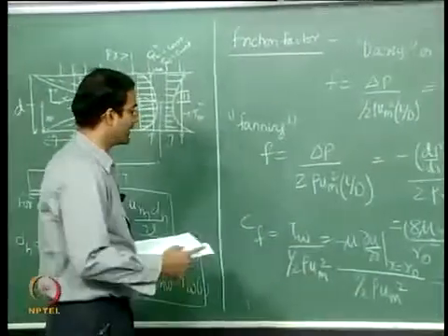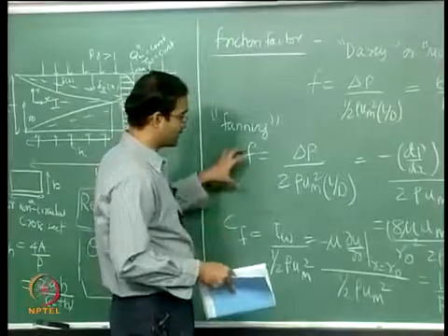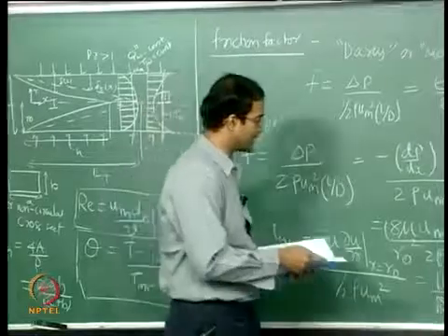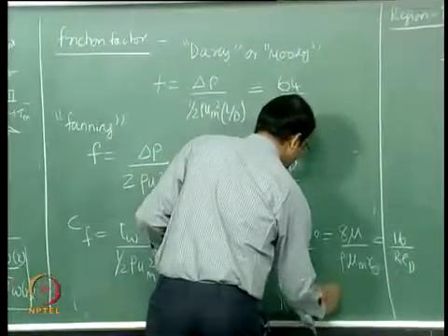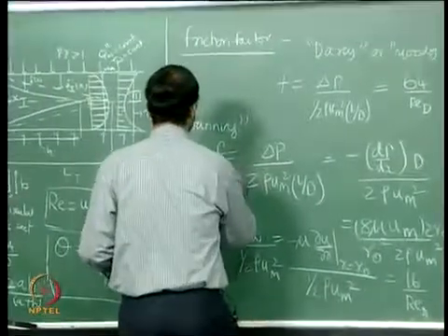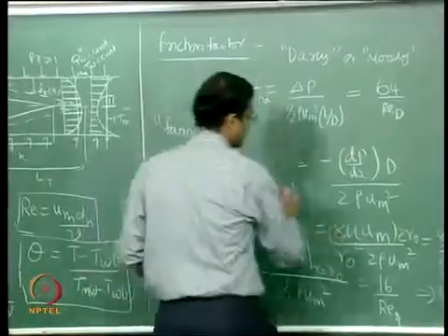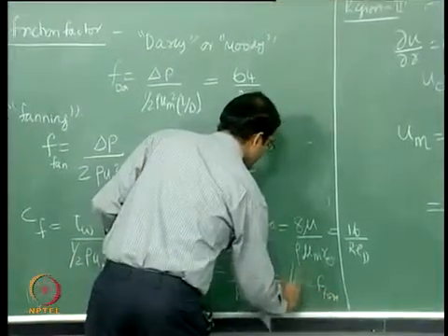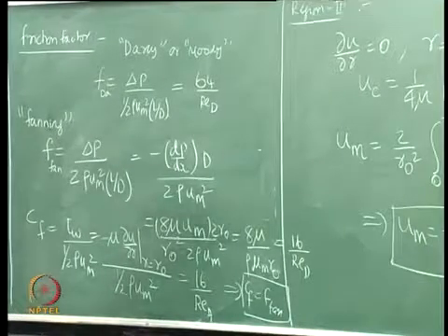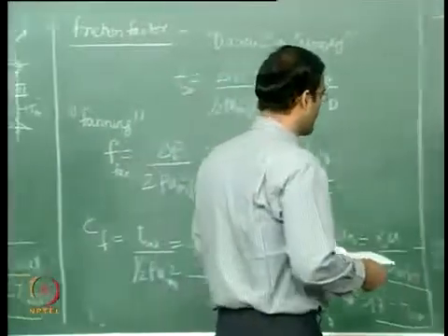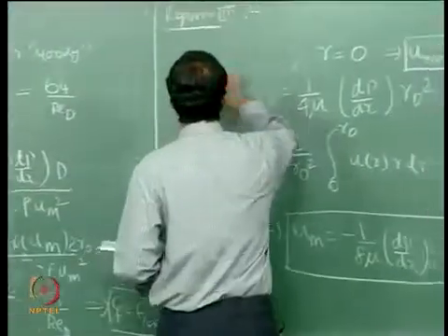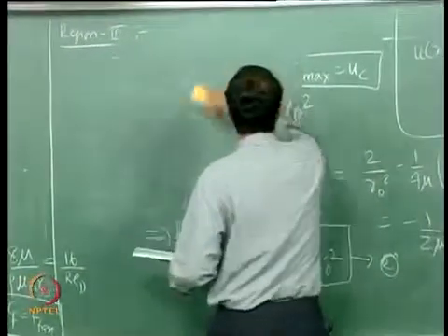So that is why the Fanning friction factor was defined the way it was: both the Fanning friction factor and skin friction coefficient become identical. Therefore for the fully developed case your Cf is equal to your F, let me call this F Fanning here to differentiate it from F Darcy. So this is another important result that you should remember. Now if you plot the friction factor, I think all of you know how it looks. This is called the Moody's chart.